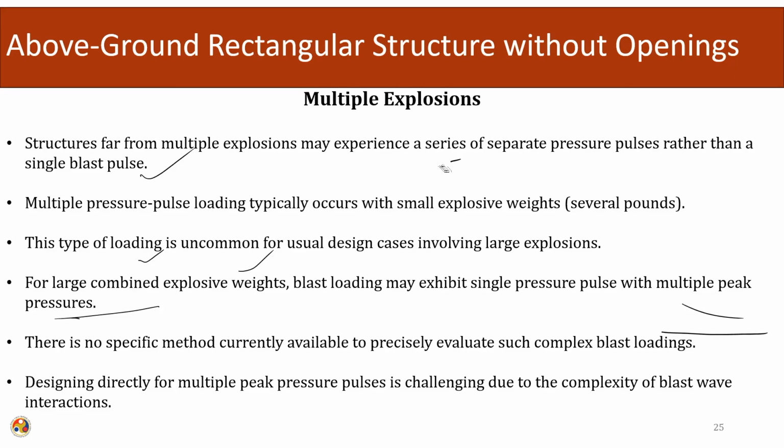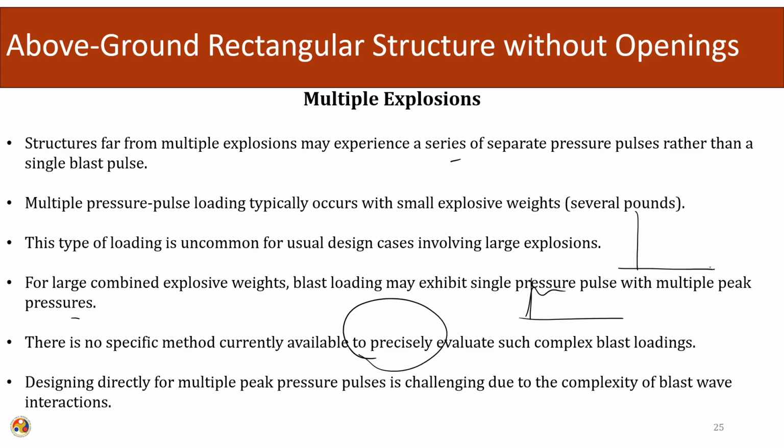A single blast loading, as we have seen, involves many assumptions. We are assuming uniform blast loading, an above ground structure, and rectangular structures, and when this combines with the multiple explosion case, the analysis becomes much more complex. Right now we do not have a precise methodology, we do not have a cookbook to evaluate this. Either we can do a finite element simulation, or